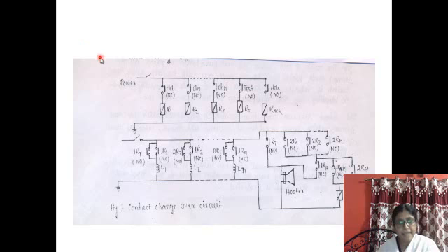That means the relay corresponding to that particular control loop is in normally de-energized state, so its contact is in closed position. And when it is energized, that means whenever any failure occurs, it will open.